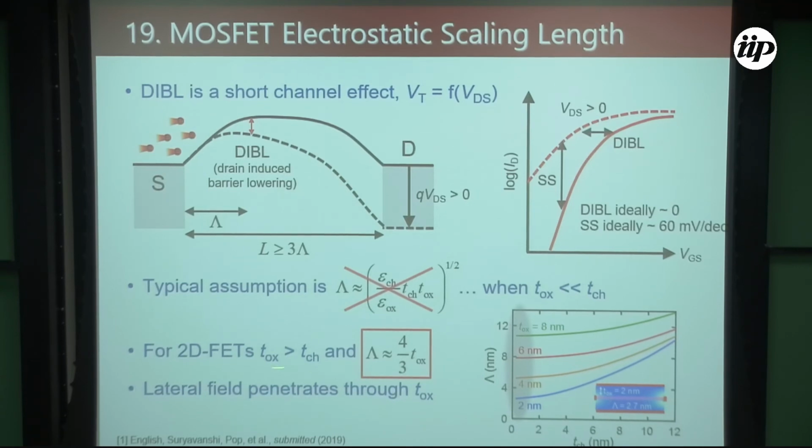So our oxides are always, always thicker. So we actually find out that equation is no longer good. We derived another equation. It turns out to be simpler. We backed it up with all kinds of simulations. And the explanation for that is that most of the electric field actually travels in the oxide right now rather than inside the semiconductor, because the oxide has become thicker.